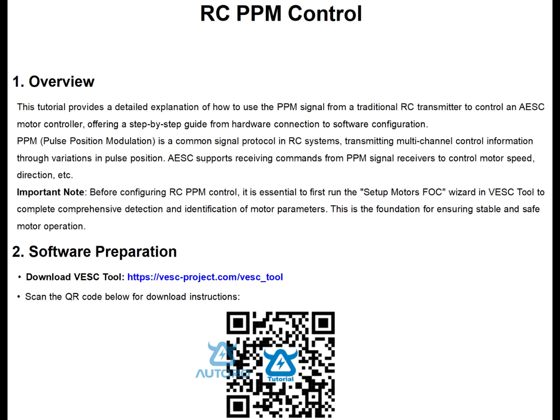Important note: before configuring RC PPM control, it is essential to first run the Setup Motors FOC Wizard in VESC tool to complete comprehensive detection and identification of motor parameters. This is the foundation for ensuring stable and safe motor operation.